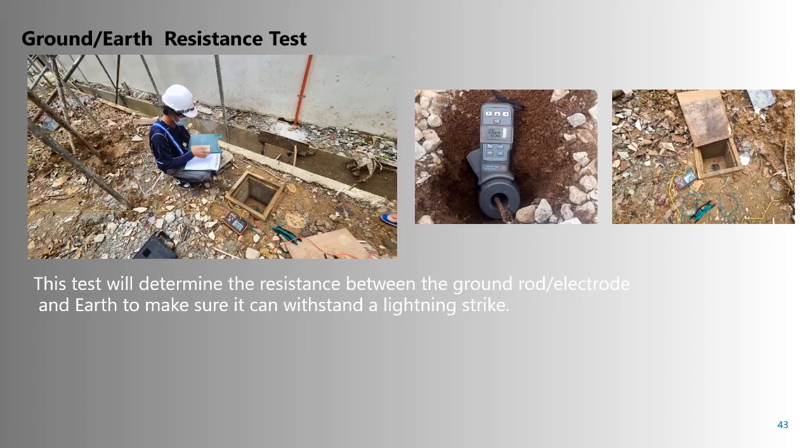Maybe the soil quality here in the Philippines is a main reason for it. But you could do your soil resistivity test before going on the design of your grounding in your country.